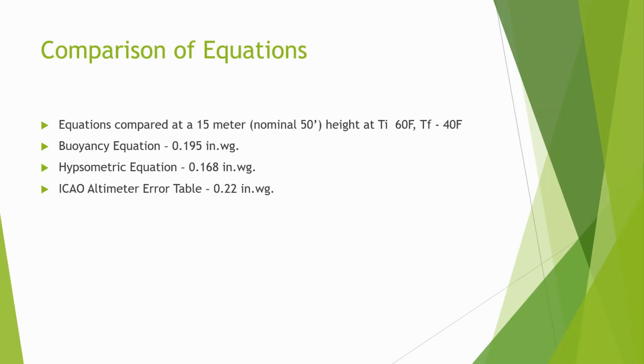Comparisons of equations. These equations don't necessarily render the same result. I went through these calculations and found that this was the result of these three equations. The buoyancy equation is the equation that I have decided to use for building static pressure correction.